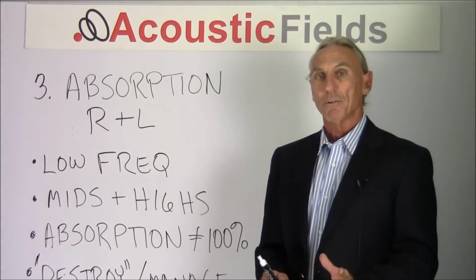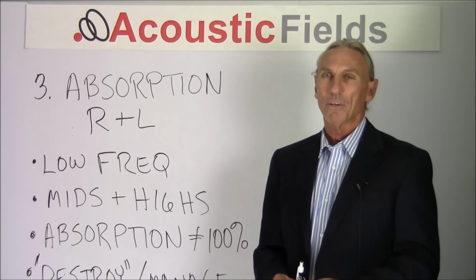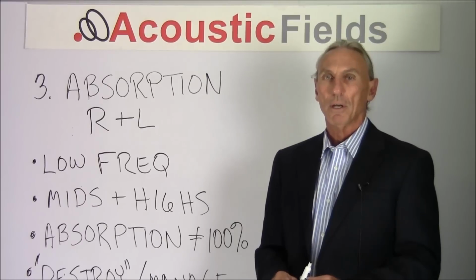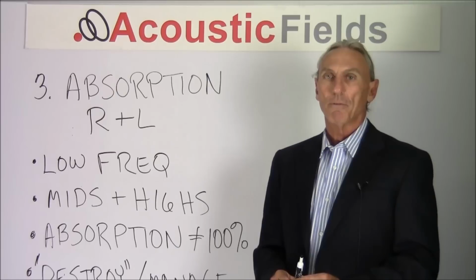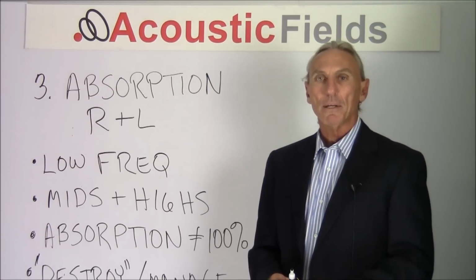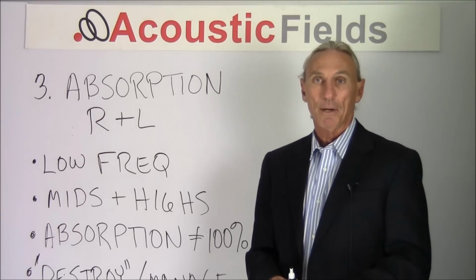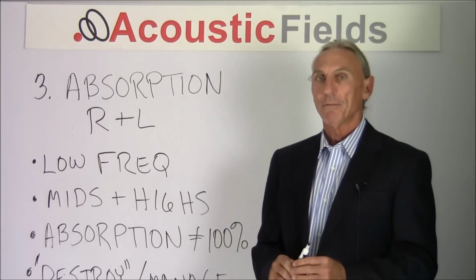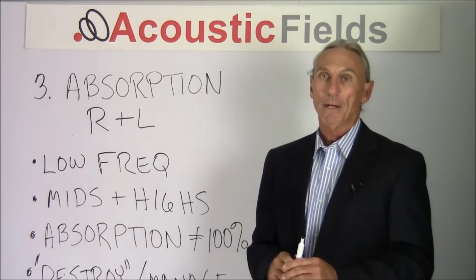Now, I'm not saying destroy energy, but changing it to heat, to a different form, in effect, is kind of destroying it. We take the acoustical energy through absorption, run it through a box of building insulation, open-celled acoustic foam, and we convert it to heat, and it's changed form. So in essence, it is destroyed musically because we can't hear it any longer. It's been changed to heat. So we want to be very, very careful about destroying energy, quote unquote, in order to manage it.